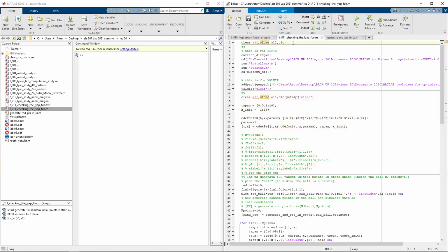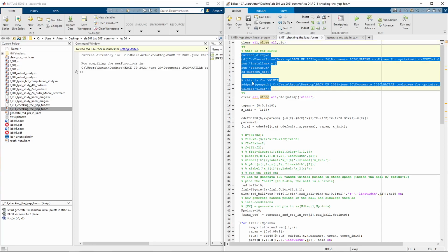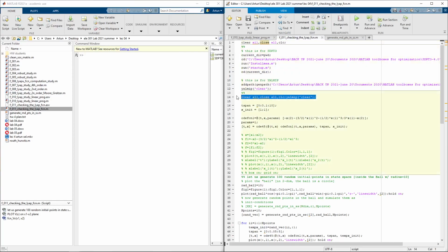run this, and please ignore this section, okay? All right, we just started from scratch, right? And this is t span, starting from 0. You may not use that if you don't assign any dt, the incremental time duration. MATLAB will automatically compute some, quote unquote, optimal incremental value, and that will be the variable dt as well.